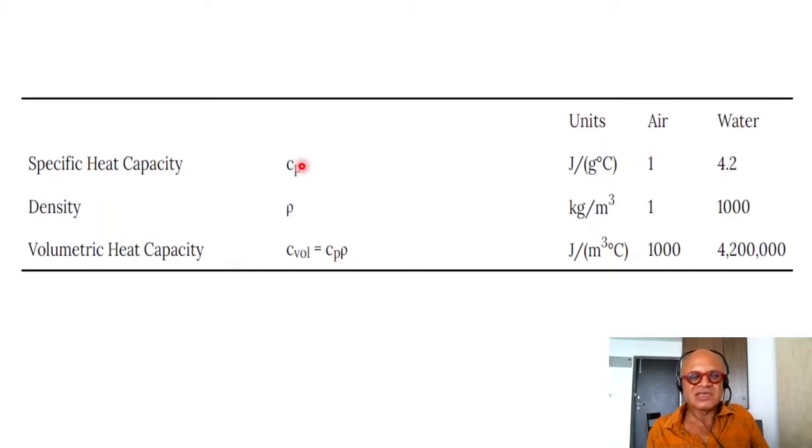So these things are details. You can also have volumetric heat capacity where you keep the volume constant. For fluids, that is an easier convention to shift between Cp and Cv. So Cv and Cp are related through density, obviously. There it is measured in joules per meter cubed per degree centigrade. So instead of mass, you measure it in volume. It's volumetric heat capacity, and density of course is measured in kilograms per meter cubed or grams per centimeter cubed, and so on.